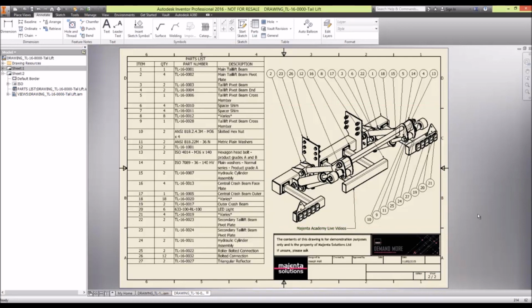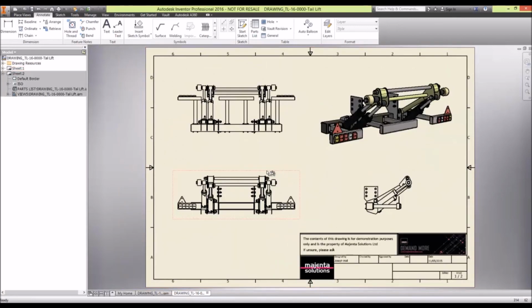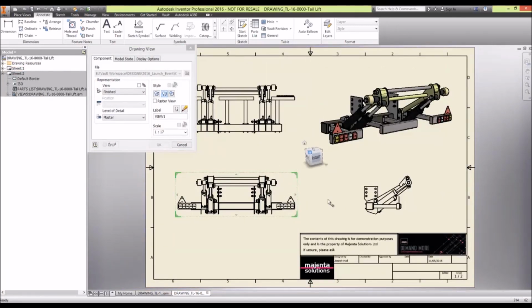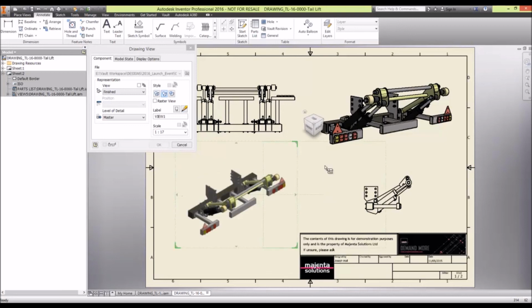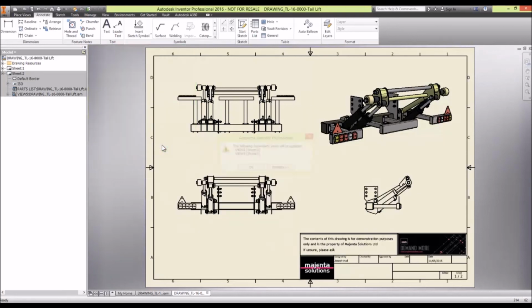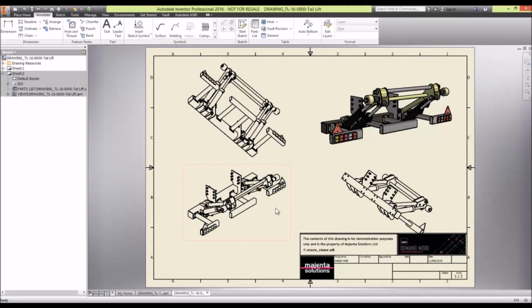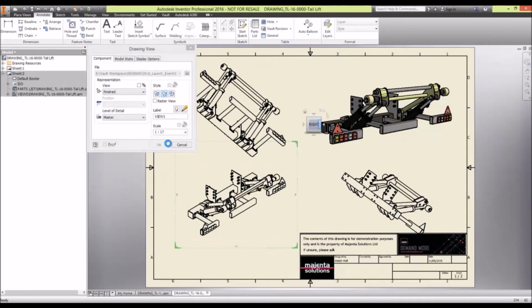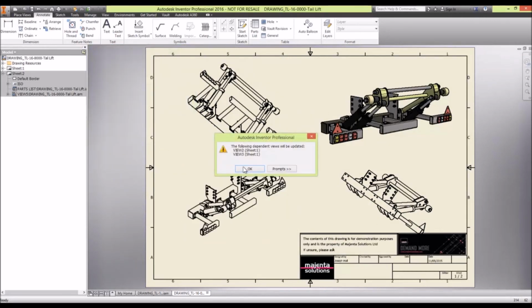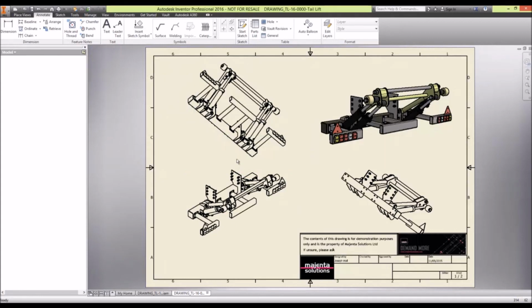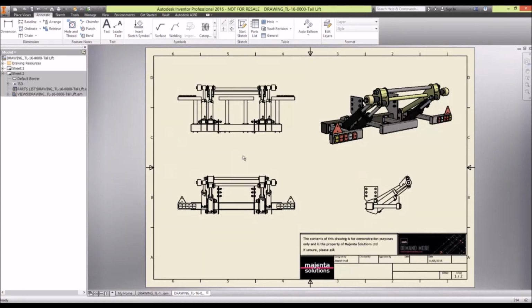So speed documentation, the main enhancement here is what I've shown you on sheet 1, the really quick ability that we have to click on change a drawing sheet, and it will change everything else. So in this instance, if I change that and click OK, now it's going to say everything else has changed, so I need to update it, and it will move these two views because they are dependent as well, and they all then update. So having this ability to create this documentation really quickly, given the prompts, will save you a lot of time. It now makes drawings a little slicker.